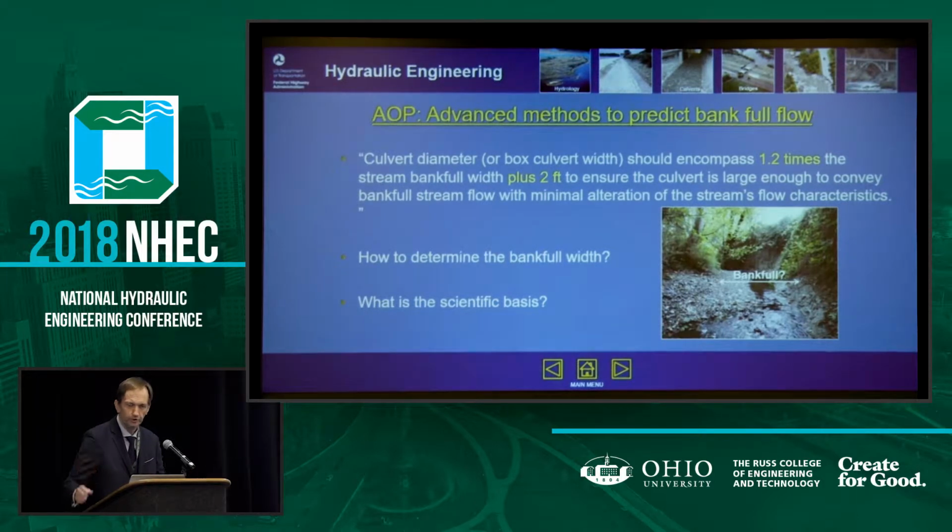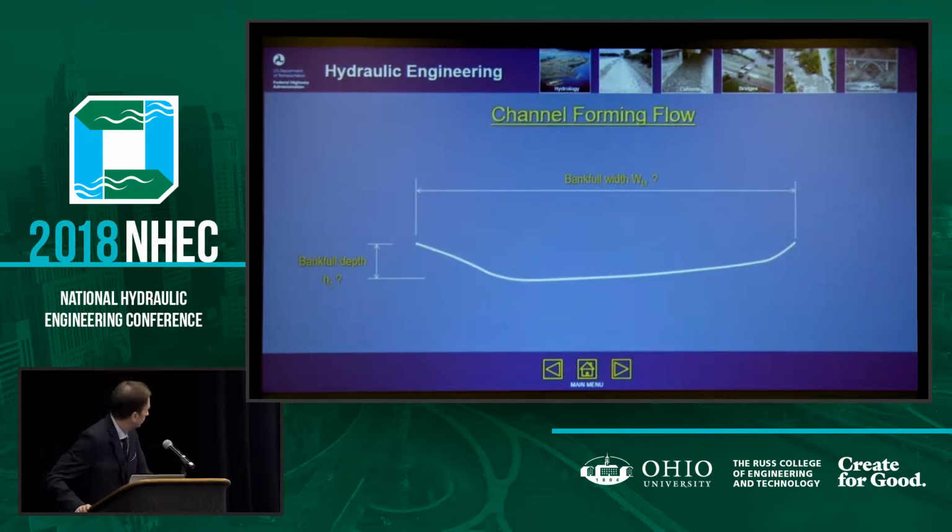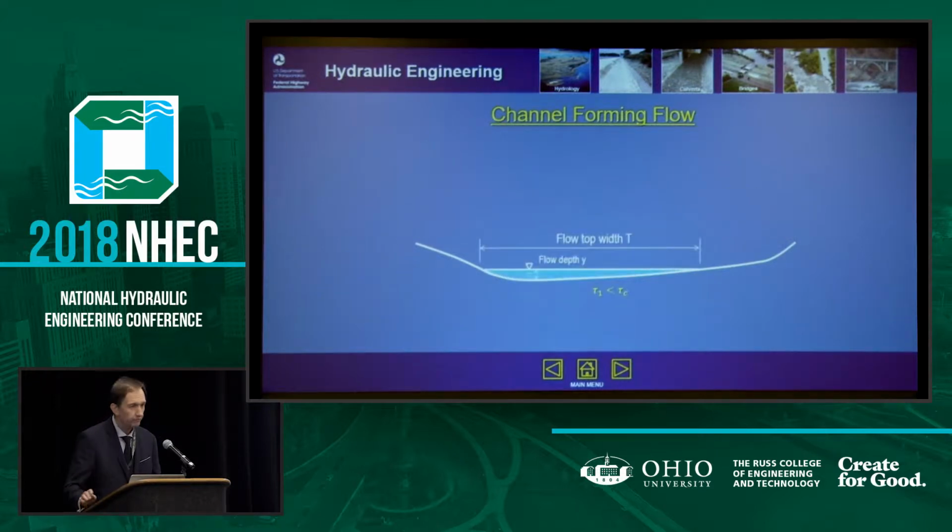Again, lots of things we heard about already. So let's start with that concept. This is a general channel geometry where we don't know at this point what the Bankfull width is going to be, and we also don't know what the Bankfull depth is going to be. So let's run some flow through that channel and measure, in a three-dimensional model, what the shear stress distribution is on the channel bed.